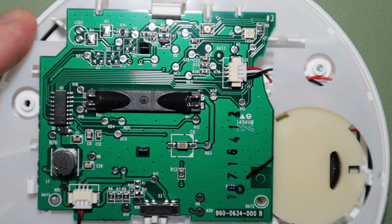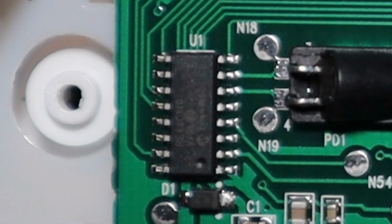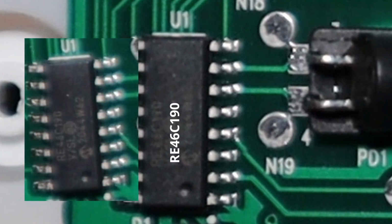Getting back to the board, the integrated circuit appears to be an important component as everything seems to run to it or from it. The integrated circuit is essentially a smaller electrical circuit on a semiconducting material performing the same function as the larger circuit, basically a circuit within a circuit. If you look a little closer at the markings on the integrated circuit, we can see RE46C190 printed on the face of the component, handing us another clue.